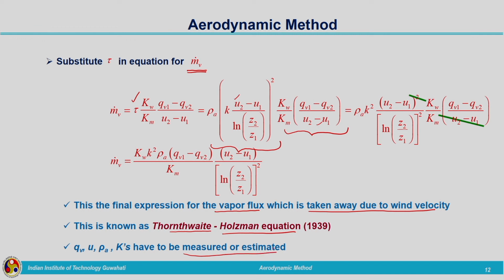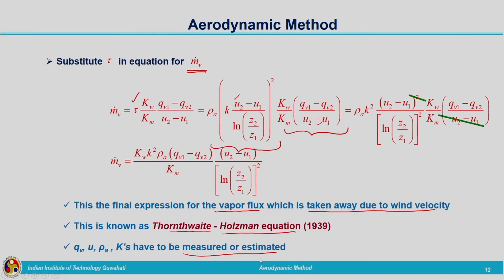Okay, specific humidity, wind velocity can be measured, specific humidity can be calculated. We are having the expression corresponding to specific humidity in the water vapor dynamics we have studied. So, those equations we will be utilizing here and we can calculate these values, or the values which are measured such as wind velocity at different levels, or it can also be calculated by using different formula relationships. So, those equations will be utilized and we can finally calculate how much is the vapor flux taking place at that particular location.